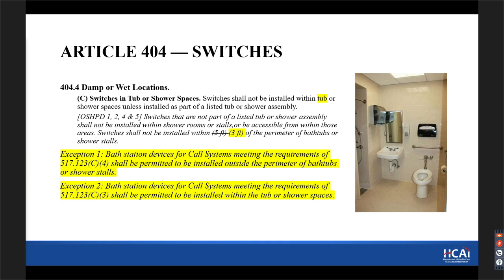We've had internal discussions, and our understanding of the shower is the threshold of the shower. So regardless of whether it's a shower head that can be manually operated, or the drainage system in the bathroom, or the lack of a threshold, the shower area is the threshold of the shower, and the devices would need to be outside of a distance of 3 foot from that area. Of course, nurse call devices, which are made and required to be in showers, are low voltage, and are listed for that use, so they are allowed.